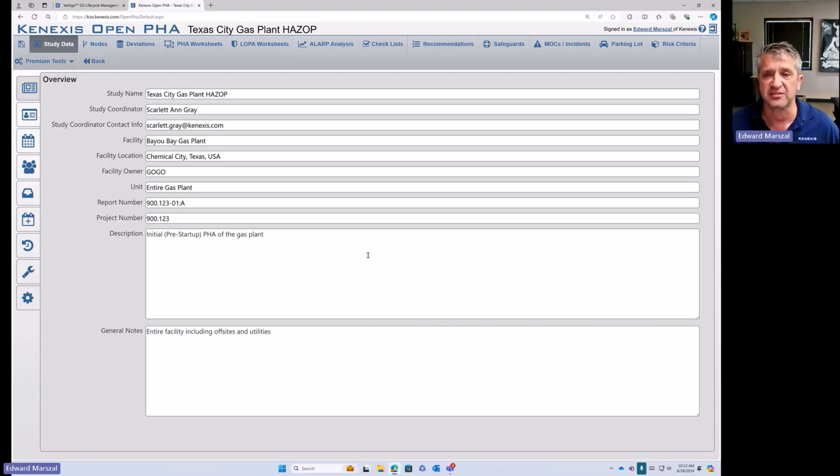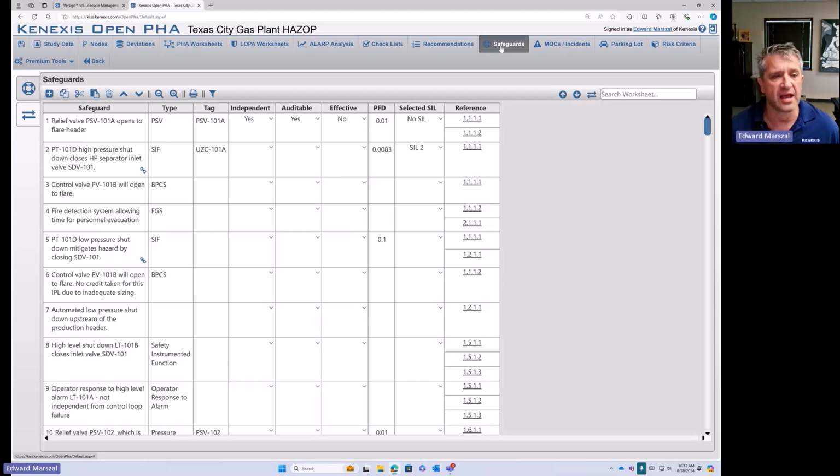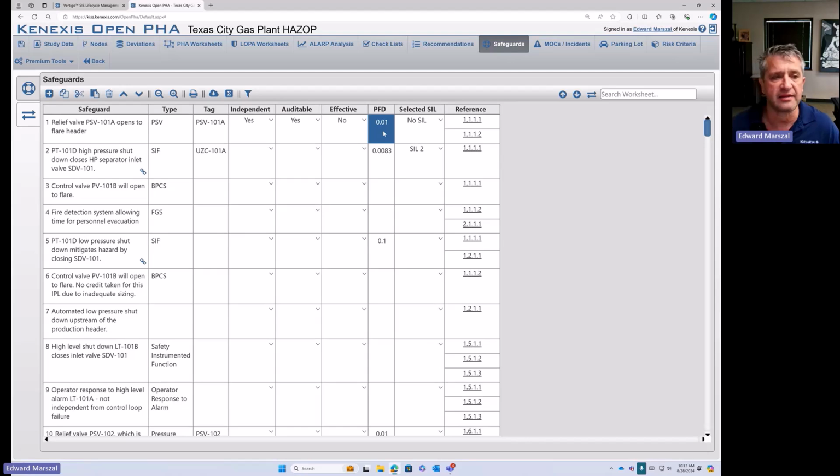and go to the very end, and you'll see that once you're done with a HAZOP LOPA study, you're going to have a list of safeguards that are referred to in various HAZOP and LOPA studies. And you have usually assigned a PFD or a SIL target to those safety instrumented functions that gives their performance criteria. And the beauty of what we're doing in KISS that no other platform is capable of is we're keeping the studies separate from each other, which allows for flexibility in the engineering process, the use, the data migration, but it links things together.